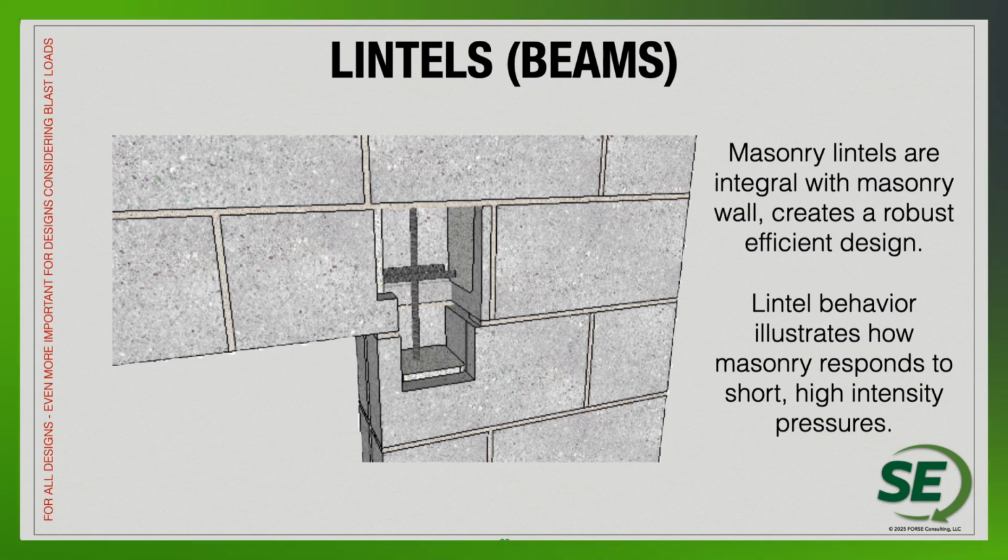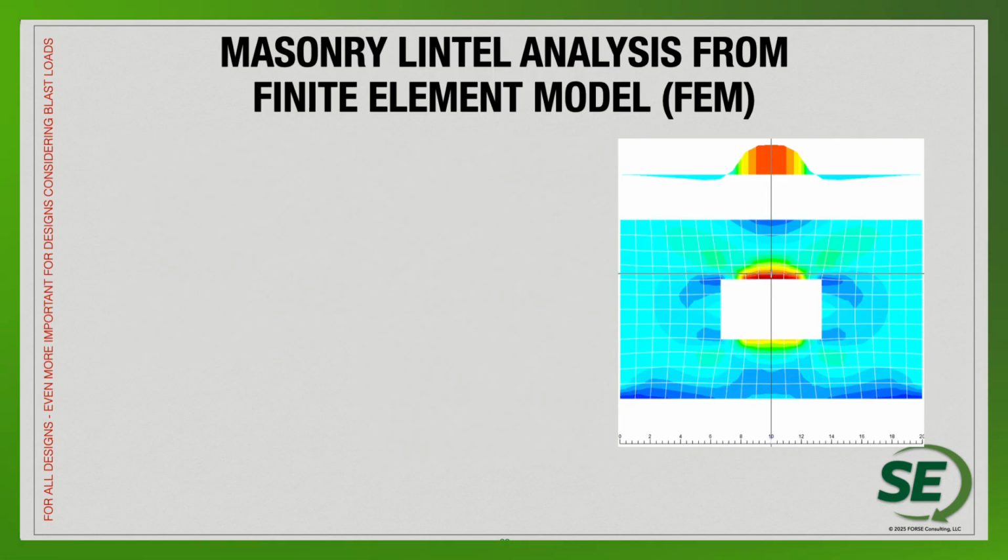Again, if we do have those openings within the masonry walls within the blast area, it's going to come with some higher stresses, higher forces. So we want to have very good continuity and elements that you can have here with a masonry lintel.